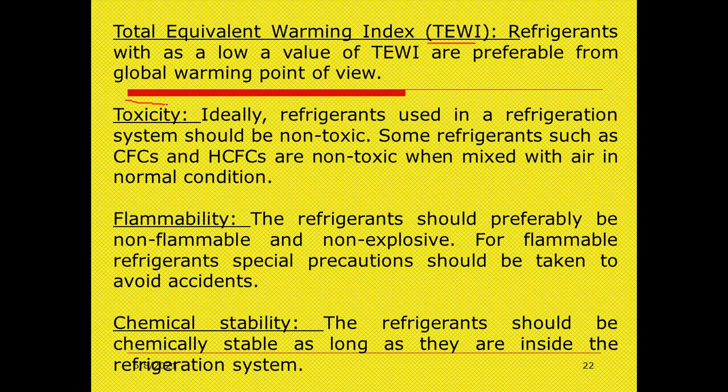Next, flammability. The refrigerant should preferably be non-flammable and non-explosive. Understood? Why? Because of safety conditions, and also because they will be at residential places and crowded places. The refrigerants they are using, either inorganic or organic, whatever, they have to maintain flammability. It should be non-flammable and non-explosive in nature.